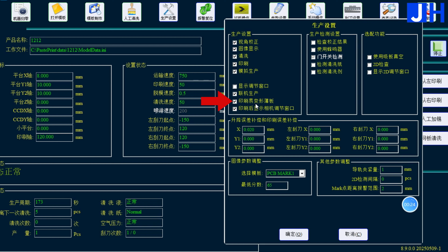This is a design feature for PCBs that are extremely thin or prone to deformation. The standard production process involves clamping the PCB first, followed by the descent of the stencil, with solder being applied onto the PCB. However, this method is prone to causing PCB deformation. If you select this function, first lift the PCB, then the stencil template descends, pressing down onto the PCB from above. Subsequently, the conveyor channel clamps the PCB in place. This secures the PCB from multiple directions, preventing any deformation issues.